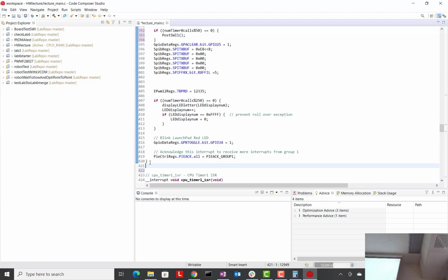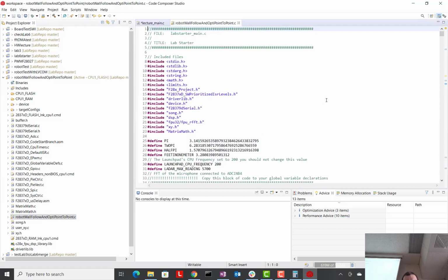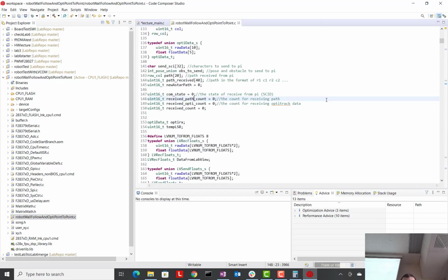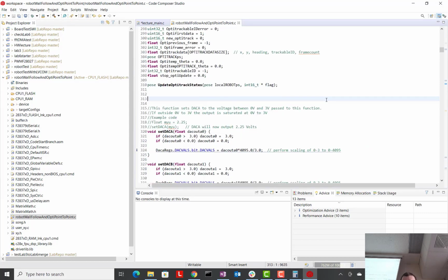You're just kind of saying, hey, hardware interrupt scheduler, you schedule this when you can, when you post it. Okay? All right, good. Now, also the difference is when you come into the software interrupt, the ones that have these three software interrupts, I'm doing a little fanciness that I found in a TI example.